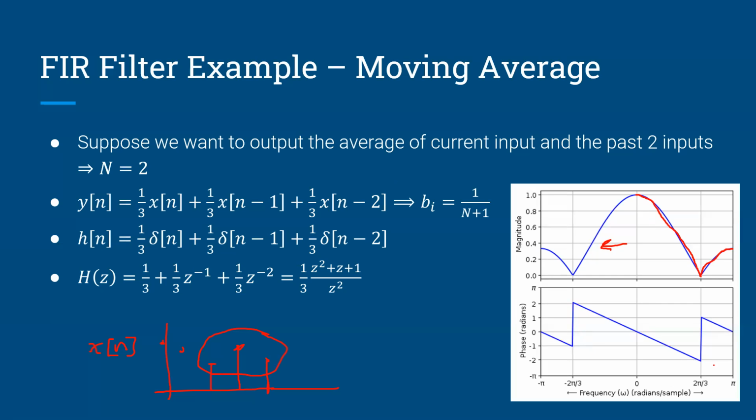it is linear, which is an interesting property because if you recall from the analog filters we looked at, the phase is not always linear. And there are some implications that has for communication systems, namely, if you have a nonlinear phase, you have what's called a non-uniform group delay. And what that does is it can distort your signal by shifting the phase of some frequencies more than others, and usually you don't want that. So that's the good thing about FIR filters, that they have a linear phase.